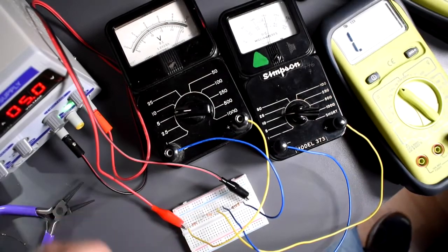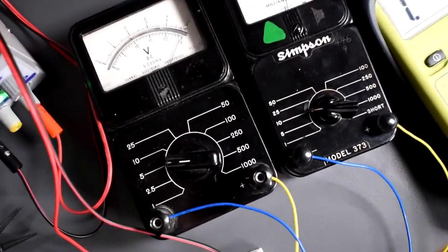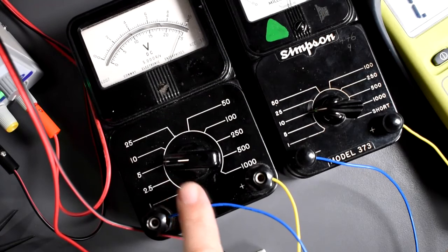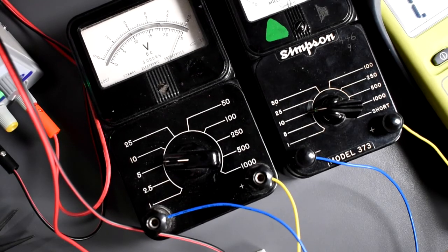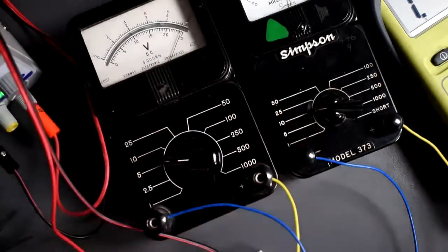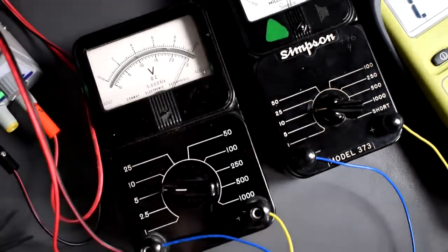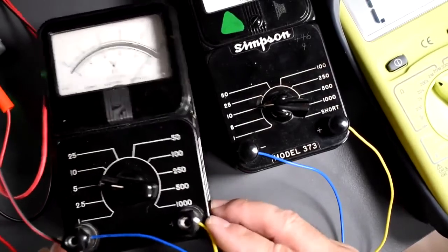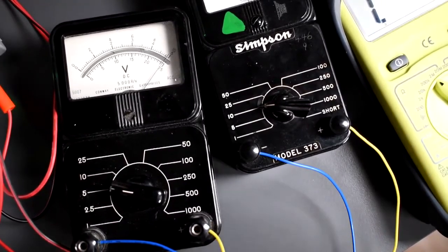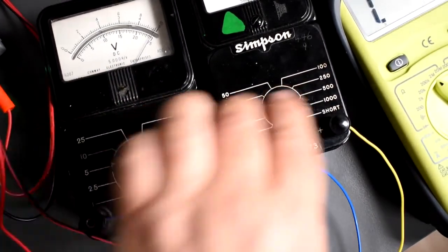All right, so what do we have here? What does this one show? We have up to 5 volts range. Let's see what is the closest thing that we have to 5. Well, we have a 5-volt range. So basically, we don't have to do any multiplications or divisions or anything like that. The needle has swung full swing on the 5-volt scale right here. Can we see it? Okay, there's the needle. That means it's showing pretty much 4.9 volts, but this is not a very accurate piece of equipment. It's probably 50 years old now.